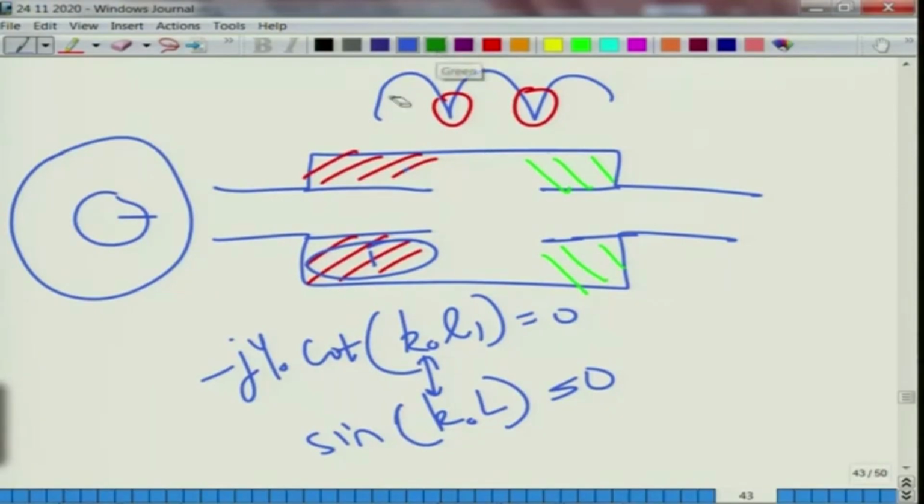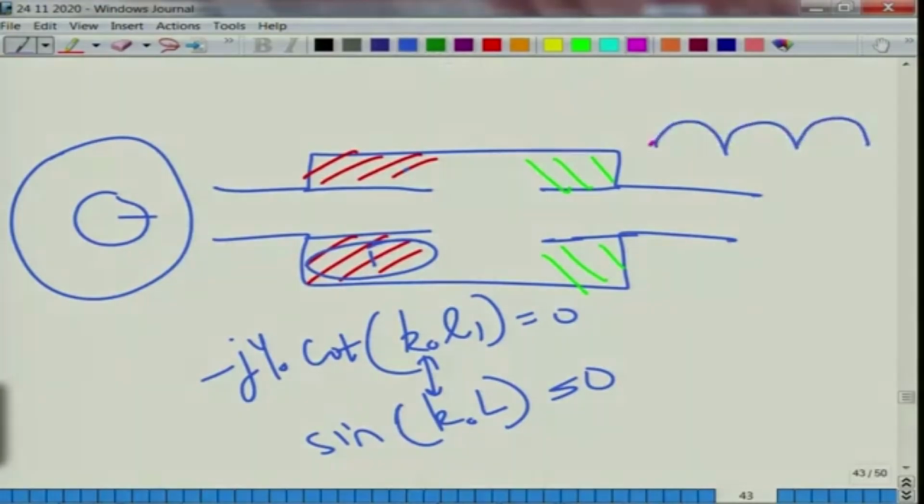So, the resulting pattern probably would be, if this is the expansion chamber, something like this, and we can similarly tune the length of this to get this, and the third peak, third trough can also be uplifted. The idea is that the resulting pattern would be a broadband attenuation using just a planar wave analysis and by wisely choosing the quarter wave resonator lengths based on planar wave propagation.